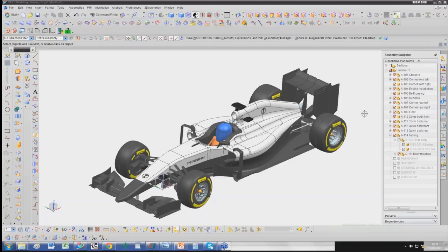No, exactly. Crosswind optimization is something very important. The car is not always in line with the wind on a racetrack, and in corners it's never aligned with the wind. It's always at an angle, because the car is sliding on its tires. So you can have angles up to 10 degrees, but typically 5, between the wind and the car. So it's important to look at the car at crosswind angles. It's definitely something we are doing as part of the development of the car, and CFD is a very good tool for that. But you need to simulate the complete car in this case.